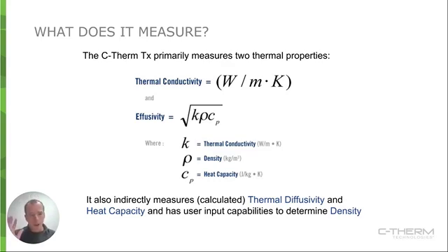But what's different there is your hand is a heat source, and it's the effusivity property of those different materials you're coming in contact with that is defining the interfacial temperature when those two different bodies at different effusivities meet. So it's the effusivity that will determine the interfacial contact temperature. And so it is the thermal property that matters most when we're trying to understand the characteristics of touch. And there's a broad base of application for this, but most of it relates to applications in textile and related goods. It does also give us the ability to derive other thermal property data.